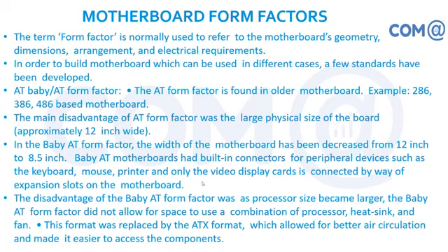This is very old. The main disadvantage of the AT form factor is that you had more components, and because of that, there was more heat dissipation and more disconnections. Because you move the computer, the components get loosened, so your connections will be dropped. If there is more dust, the tips of the IO connectors will get rusted out.